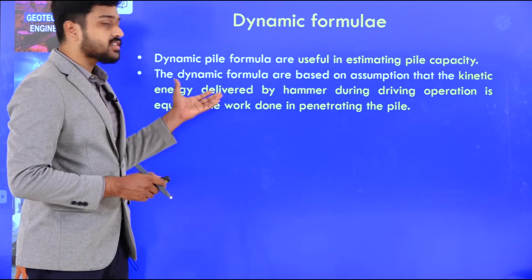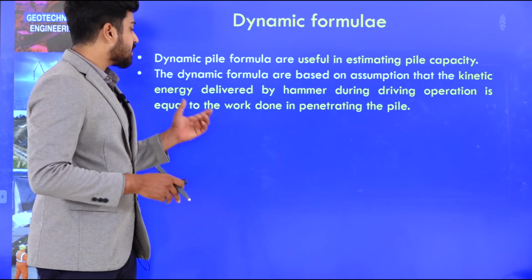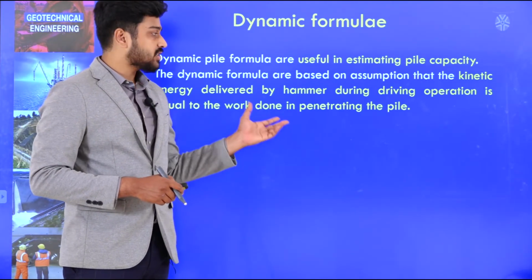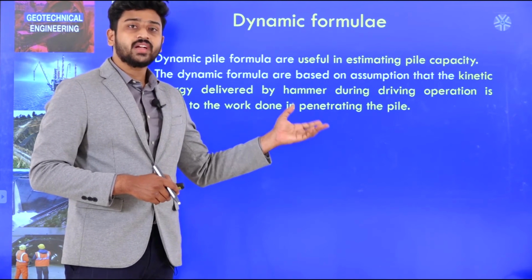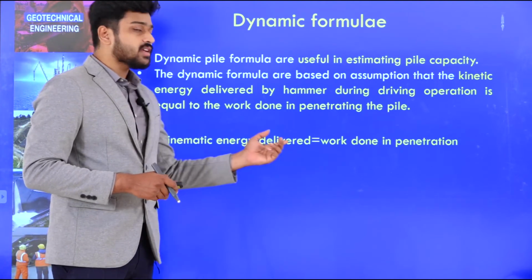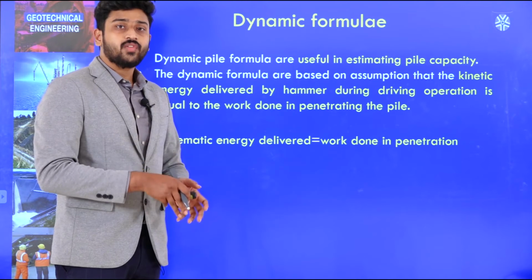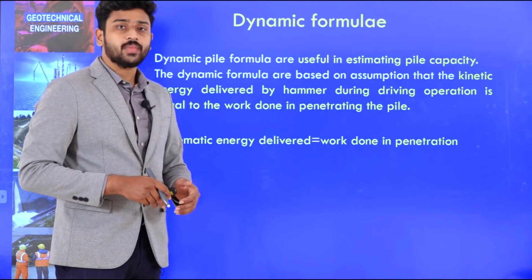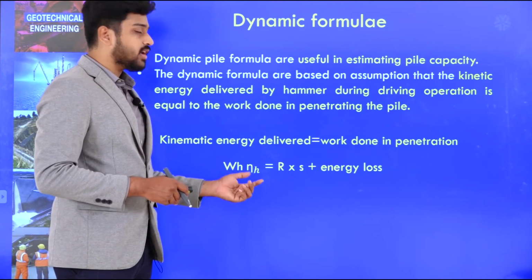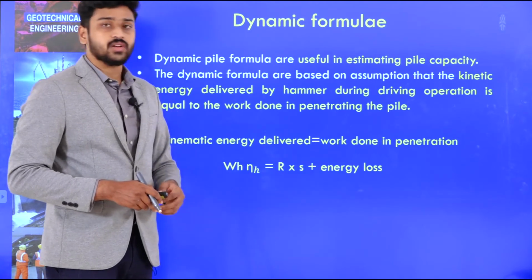So, this kinetic energy delivered by the hammer during the driving operation is considered equal to the work done in penetrating the pile through the soil. So, that means the kinetic energy delivered is equal to the work done by the driving force for penetration of the pile. This is given by WH into eta H equals R into S plus energy loss.